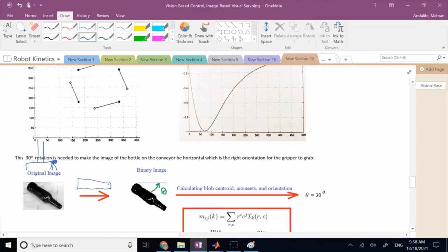So what should I do? If I want to see this guy completely horizontal, right? Then that object is fixed on the conveyor. One of the things I can do is to change the orientation of the end effector, right? So say, hey, let's spin this end effector so that it is now rotated like this. And if it does, then the end effector can go down, the gripper can go down and properly grab it.